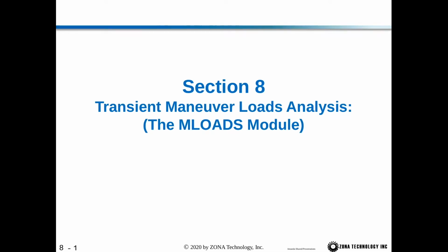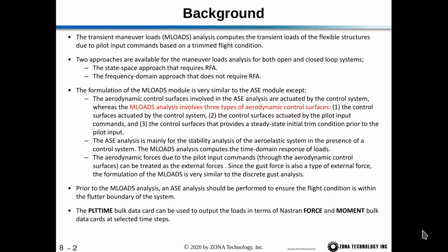Let's continue ZAERO training with Section 8, Transient Maneuver Loads Analysis, the MLOADS module. So first we'll go over a little background. The Transient Maneuver Loads Analysis computes the transient loads of the flexible structures due to pilot input commands based on a trimmed flight condition. And we have two approaches available for the maneuver loads analysis for the open and closed